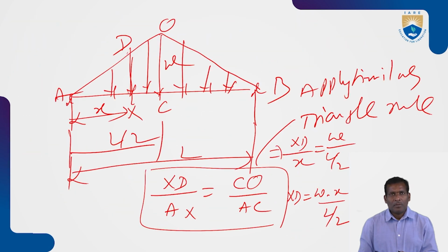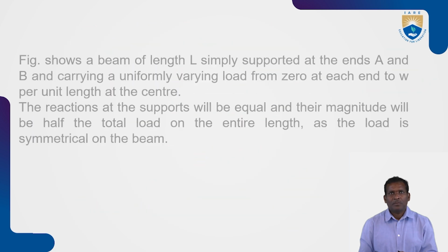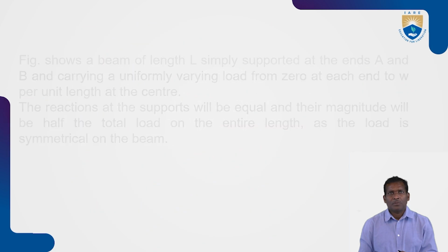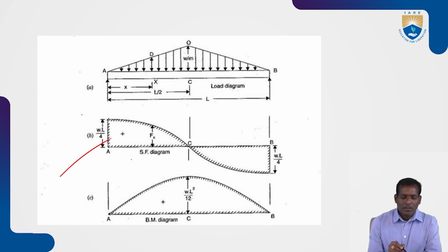So here we calculated the shear forces. Now draw the shear force diagram. At A, the shear force is WL by 4, a positive value.